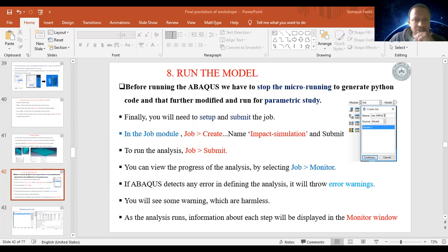The power is not specified, or the specified value is equal to or smaller than 0. This is not allowed in Abaqus. So this shows that I made a mistake. Why? I used the BK criteria, the power law BK criteria, and I didn't submit the BK exponent to the system, so that it is telling me that I made a mistake in my work.